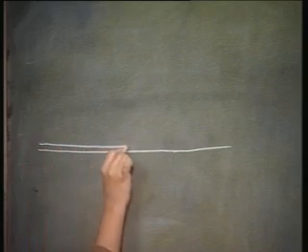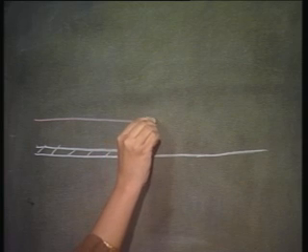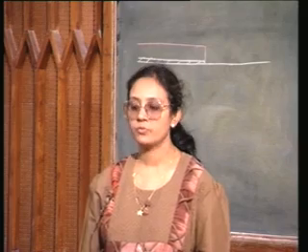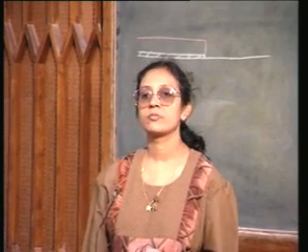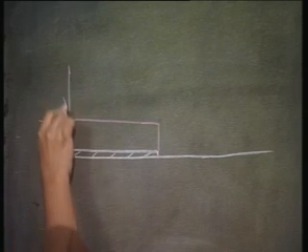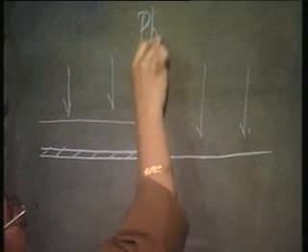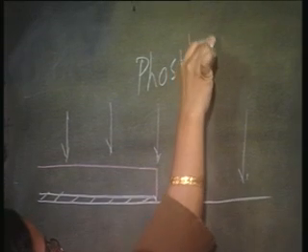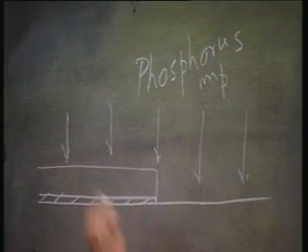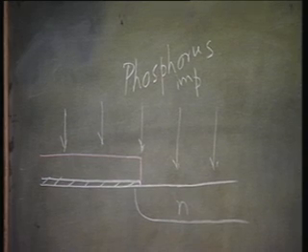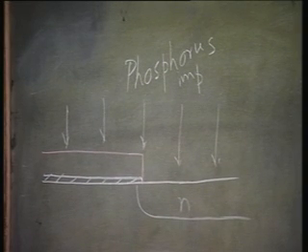Okay. The only thing I do is protect certain regions using an oxide nitride mask, and then, in this particular case, I take a phosphorus implantation, so that you have your Nwell.